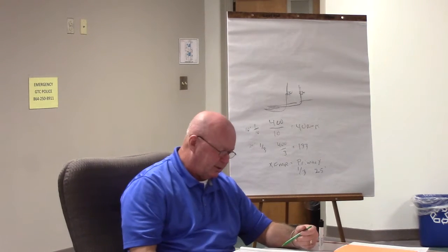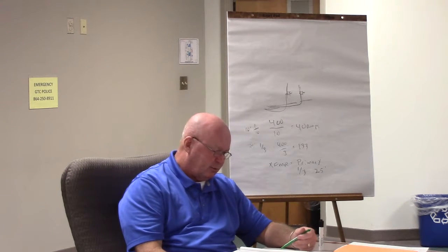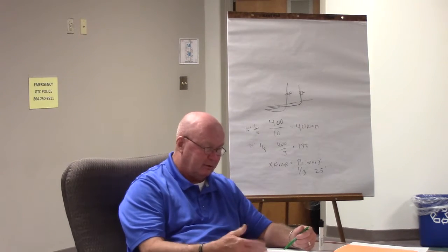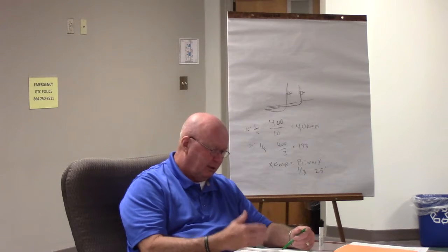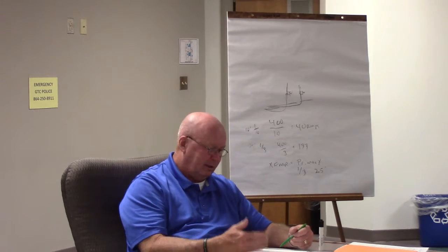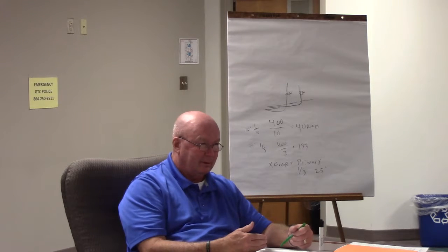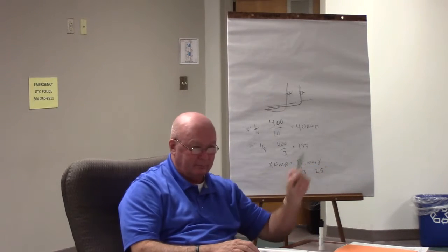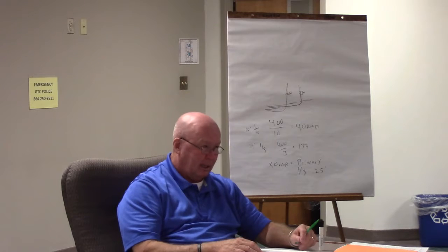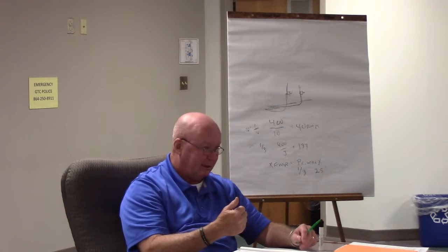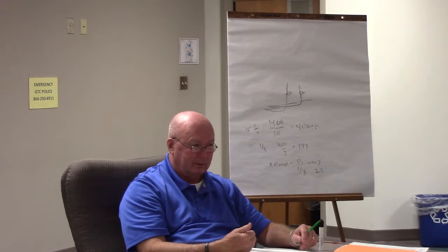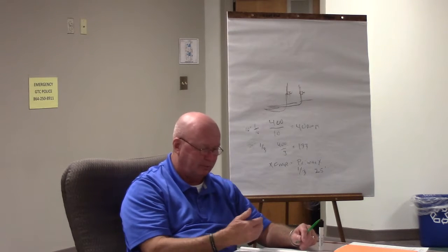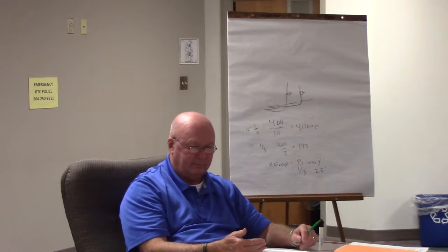Bullet point number 2, the ampacity of the secondary conductors is not less than the secondary current rating of the transformer. The sum of the ratings of the overcurrent devices does not exceed, in other words, just can't exceed it. The ampacity of the conductors can't exceed the overcurrent protection. The overcurrent devices are grouped. Why do you think that's important in a plant? We want them right there together, don't we? We don't want one over there, not knowing what it is. I mean, this guy, when he put it in, might know, but he might not be the maintenance guy 2 years from now. Somebody else will be. Number 4, the secondary conductors are protected from physical damage. In other words, we're going to put it in what? Put it in conduit. Yeah.